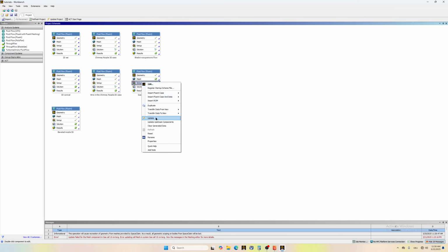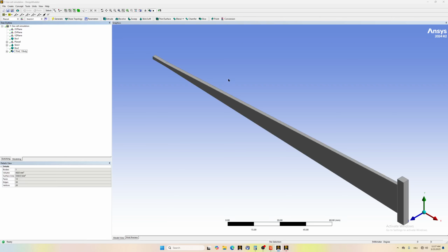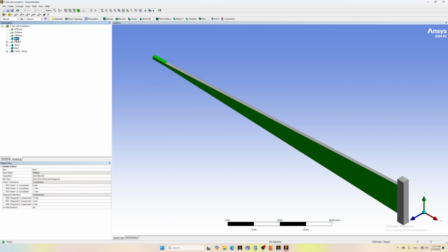The same for Ansys Fluent settings. We will start fresh with those. And now the geometry, double click or right click and open using Design Modeler or SpaceClaim or whatever is available there. All right, so what we will do, we will modify this part, what is called a box. So this part, we will make it bigger, 1 by 1 centimeter.